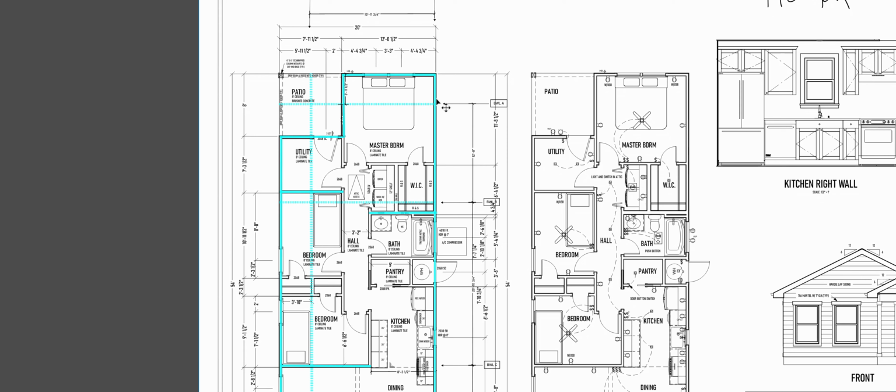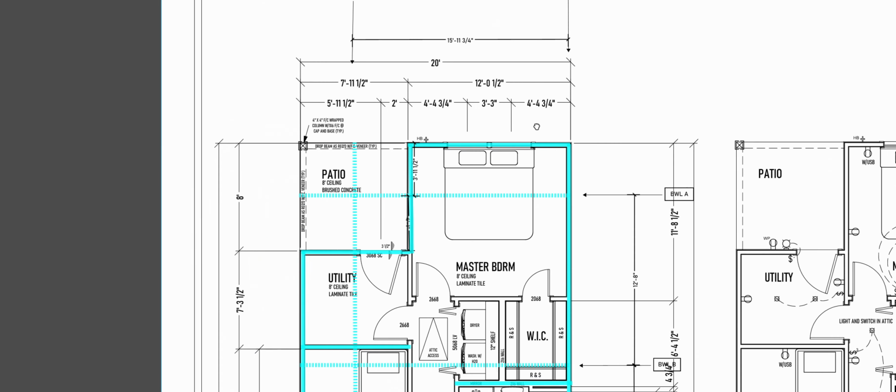So the next thing I need to do is I'm going to throw in some brace wall panels based on my minimums. So I know I need a brace wall panel, and it needs to start 10 feet from the beginning of each line, and not go farther than 20 feet apart. So we'll start with brace wall line A. So I got a nice blank sheet of wall here, so I'm going to get my circle in here so I can get a 4 foot